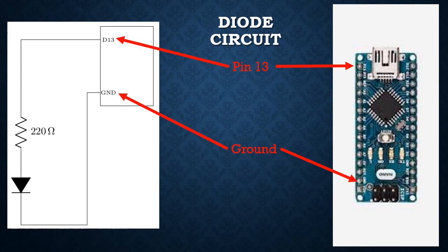So maybe you'd pick hole D. Okay, so then you have a resistor leg in 24 and a diode leg in 24, and you put the other diode leg in say row 25. It doesn't matter which hole you pick. Let's say you pick 25D.